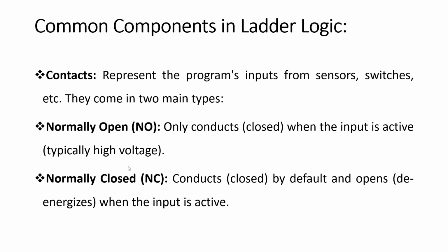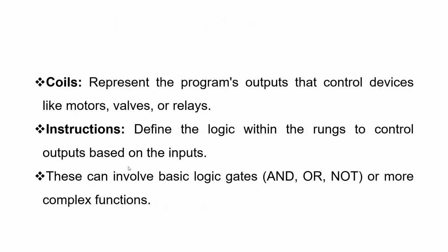So that when one comes and pushes it, you open the contacts and de-energize the coil, and then you stop the motor or you stop the system.